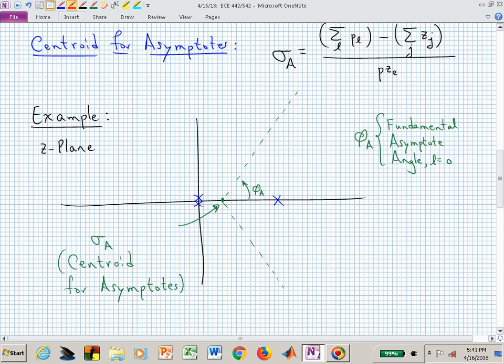That was rule 2. So now we've cut our bread, and we have certain sections of that bread, and we want to know which of those sections belong to the root locus. Is the section from the rightmost pole to positive infinity, does it belong to the root locus?